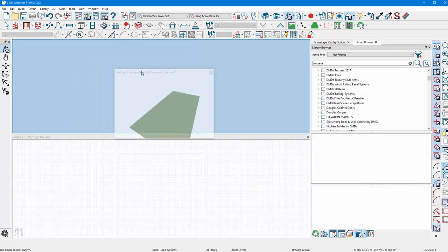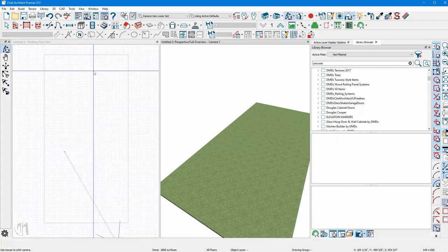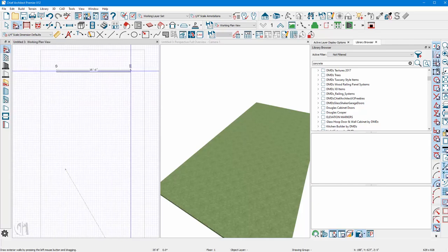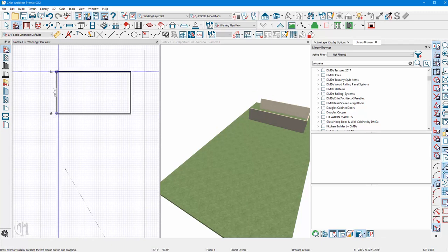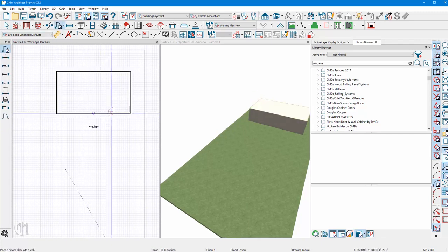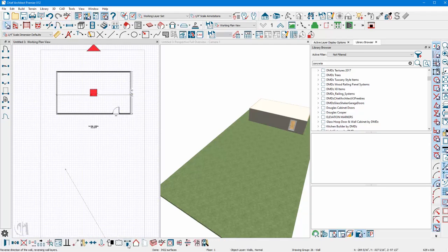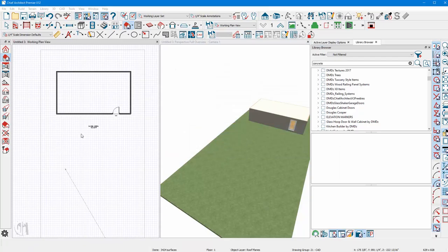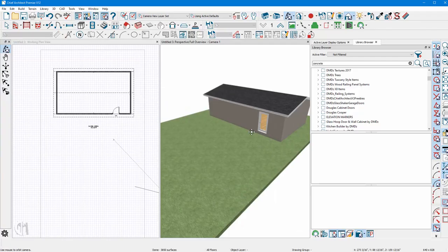So I'm going to take this 3D picture and stick it over here to the left, but I'm going to be working here on my plan file. I'm going to start by just building a simple house to give us an understanding of the height of the terrain and the house. So we'll put a door in here. I'm going to select both these two end walls and make them gable end, and double clicking the roof tool I'm going to build a roof and make sure my roof layer is turned on. Gives me a simple little house that I've built here, okay, on my terrain.